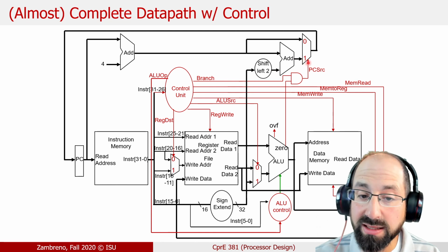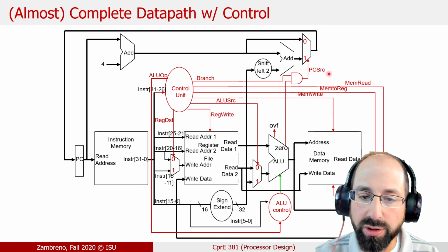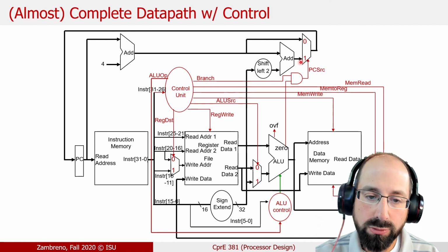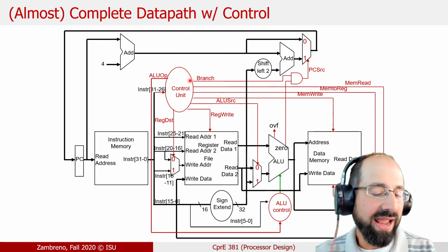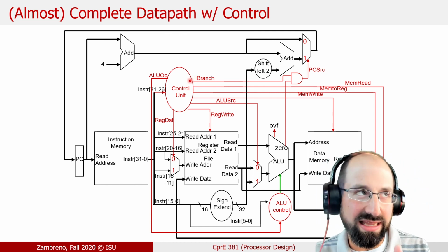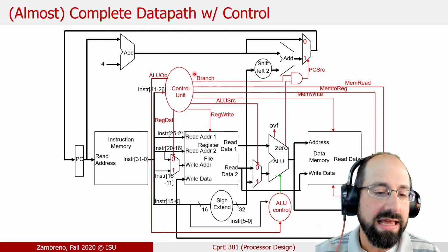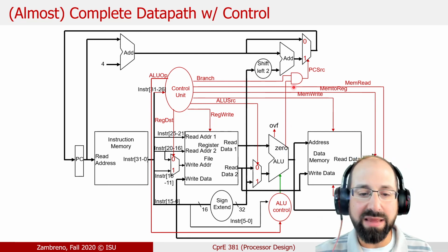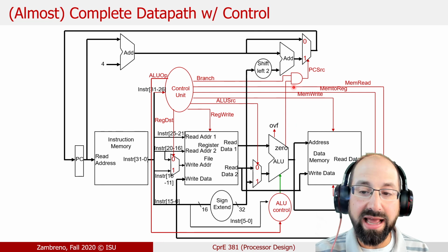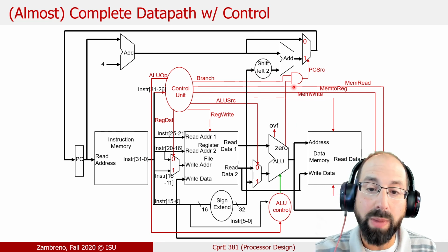And we have that mux there. This is kind of an internal signal. This is not strictly generated from your opcode. We only take our branch if it in fact is a branch instruction. And this, from the textbook, means a branch equal instruction. You'll need one for branch type of some sort, but it is a branch equal instruction and the output of my ALU operation corresponds to a 0, meaning input A and input B of my ALU are the same. They are subtracted from each other, and we get a 0 result back out.